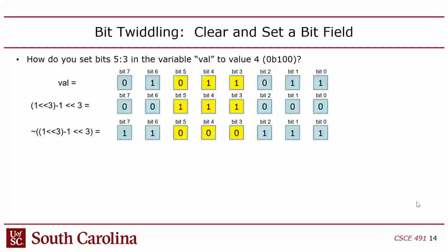When you do normal mathematical operations, everyone knows that multiply and divide have higher precedence than add and subtract, right? You learn that in grade school, and if you want to do the add and subtract before the multiply, you use parentheses. The problem is now we're mixing shift, bitwise logical, and add and subtract all in one expression. If these things are not evaluated in exactly the order that you intend, this will fail horribly, but you won't even know it.